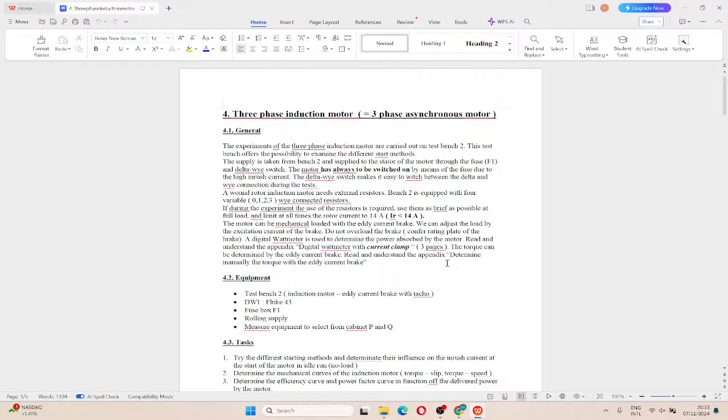So what's your question? Yeah, I had a question about the fuse break. Here it is mentioned that inrush current cannot exceed 14 amps. Yes. But I think this is a fuse. It's not a circuit breaker. I think it will allow us to have a current more than 14 in a quite short time period.